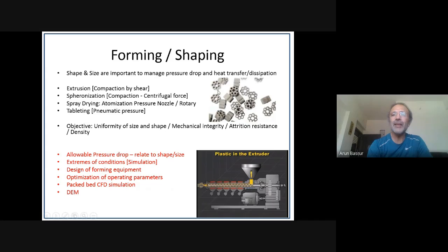So this basically is a photograph of a steam reforming catalyst which is supplied by Clariant or even Sud-Chemie. So we are joint venture partners. As you can see, it has got an intricate design and considerable voidage. The reason this has considerable voidage is because this reaction is highly endothermic and it is carried out in multitubular reactors where heat is provided by direct fired heaters. So you have a flame impinging on the catalyst tubes.